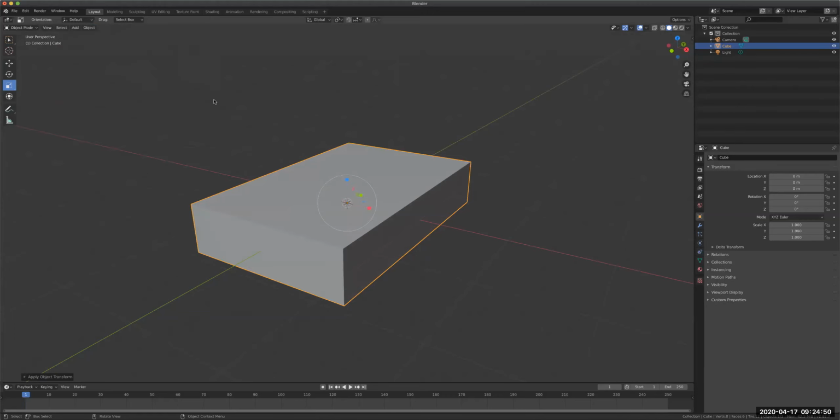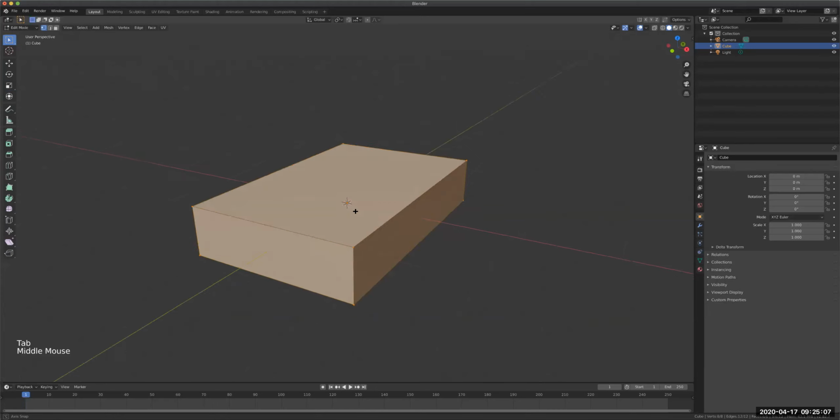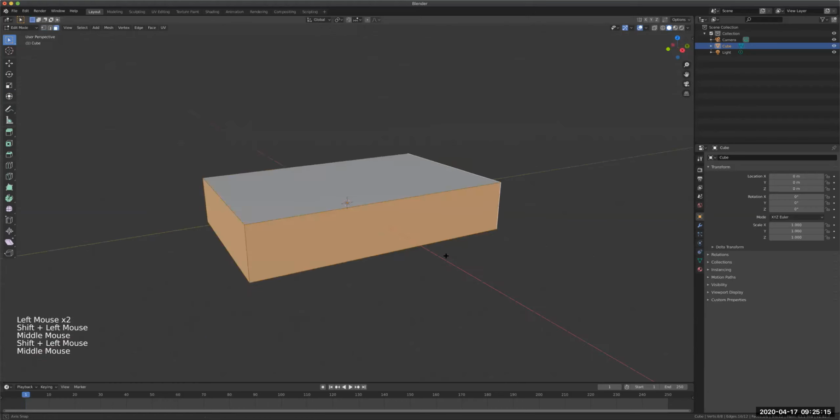It doesn't hurt. Okay. So that means whenever we try to do any modification on this, Blender doesn't think that this is still a cube. It's already a modeled object. All right. Next, I'm going to press edit mode. I'm going to click Tab right here, and then I'm going to press the face selection so that I can delete the area, because we just want the cover for this one.